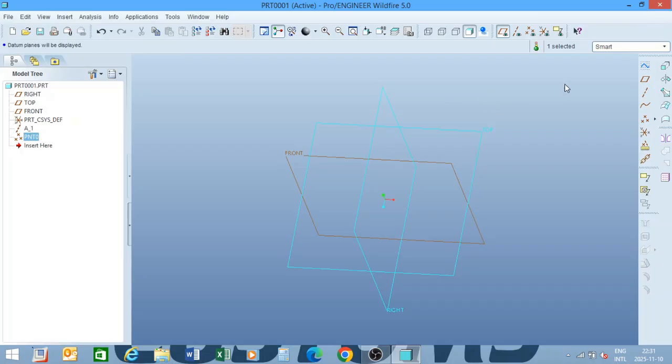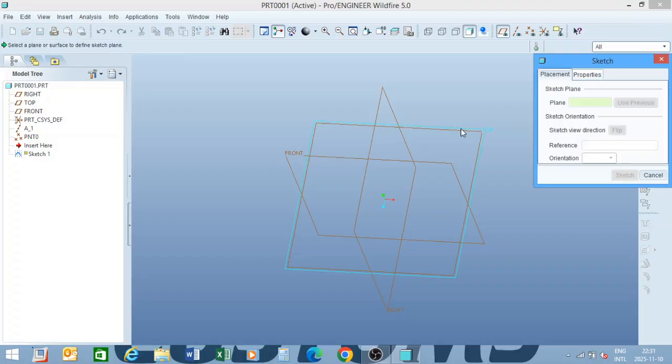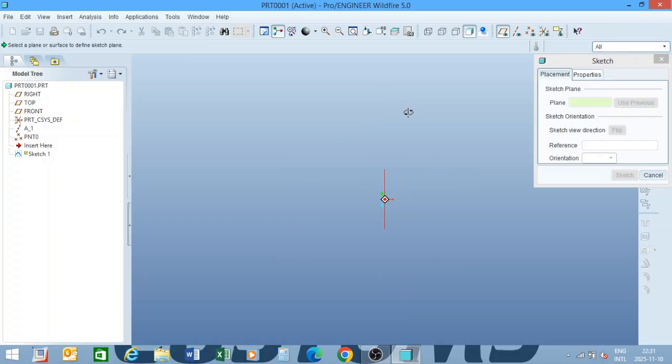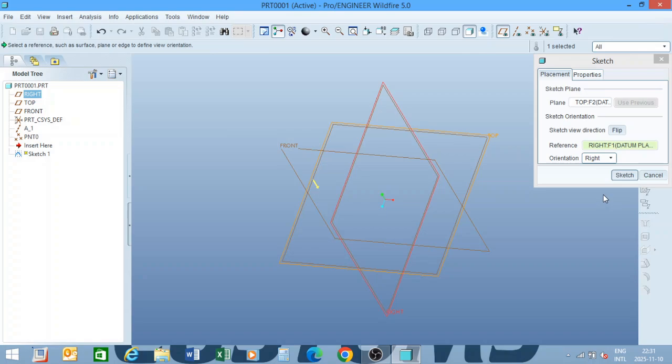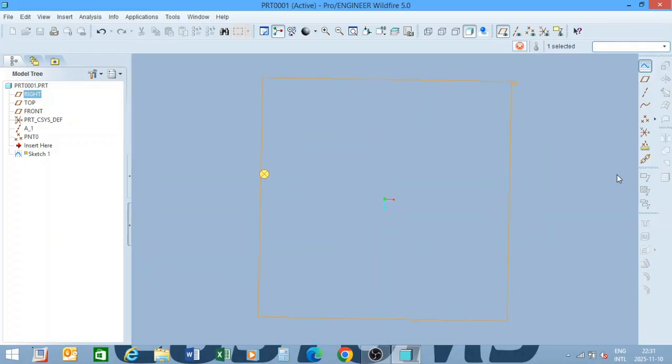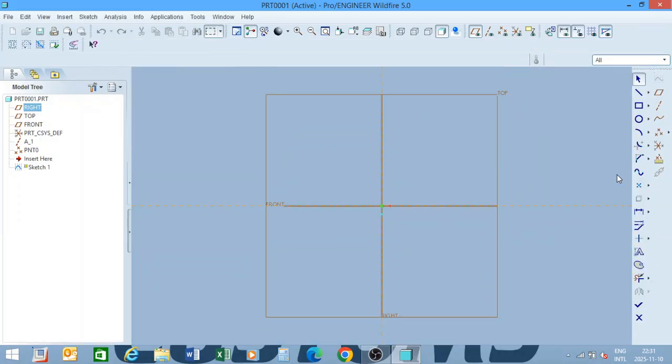Okay, so planes on, sketch function, select my plane. So okay, sorry, to draw a sketch you want to select sketch, correct. Then you need to select the datum plane where you would like to draw your drawings. So this would be obviously your ideal for top, then it's your top view. So then you click sketch and it will automatically turn it to where you need it.